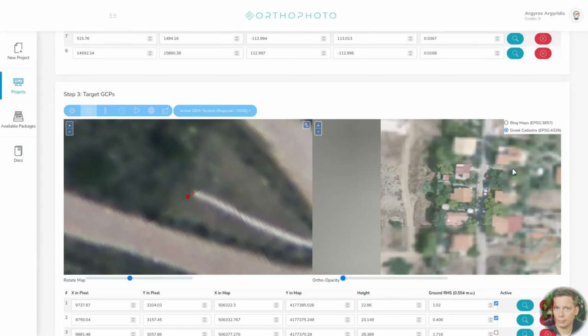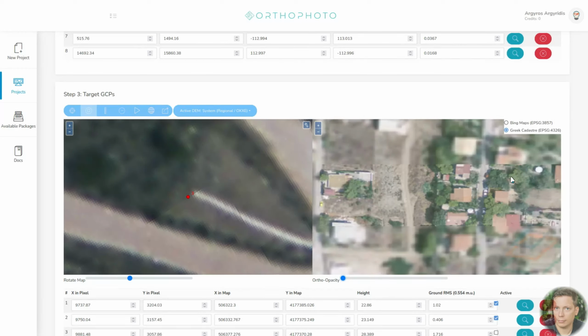If we want to achieve good accuracies, then the best option is to identify points existing on our imagery and go and collect data in these locations either with a GPS, total station or other approaches.